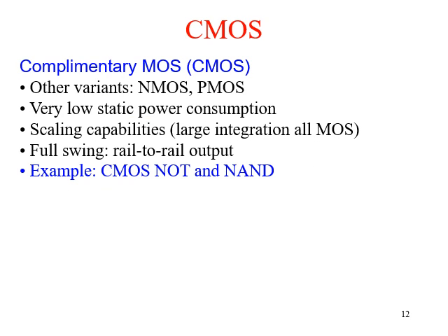CMOS, or complementary metal oxide semiconductor, is another family, and it has very low power consumption. So where we want low power, we can use CMOS, and it provides full swing. Full swing means the output range goes from lower to higher. It gives a full span, like from 0 to 10 volts, for example. And we can design NOT gates, NAND gates, and all using CMOS devices.